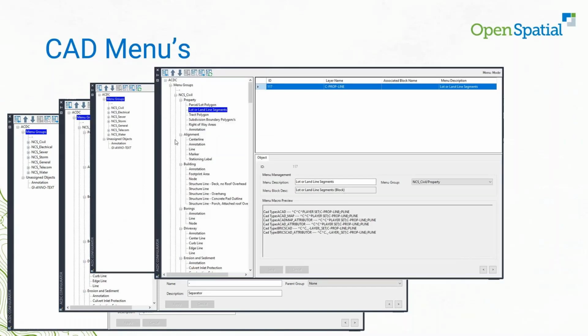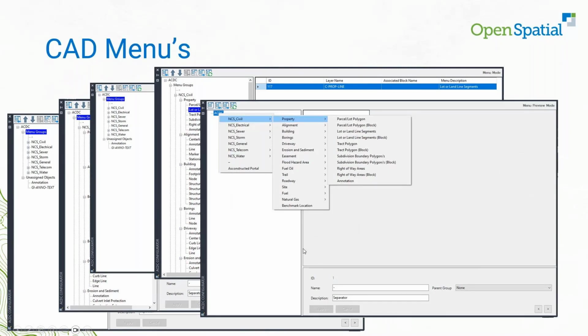And you can go in then and set up, for this given menu text entry in that group, it's this feature. So this is out of configurator. And then there's even a preview of the actual code that it's going to create in those menus. So if you're deep into AutoCAD, you'll understand that that's actually all you need to do. You could have done that manually by hand and gone in and entered those requirements that say basically set the layer on a P line and then put that in. And so you go, and we use a command called Attributor. So it just builds it out, and then you get a menu that looks like this.